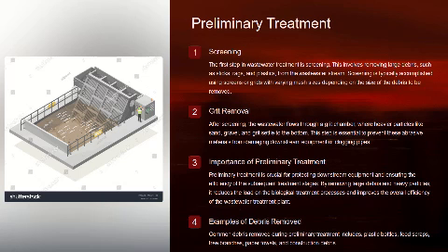After you're done screening, the wastewater flows through a grit chamber. And what happens here is that the heavier particles, like the sand, the gravel, the grit, settle to the bottom. The reason why you want them to settle to the bottom is because you want to make sure that these abrasive materials do not wear and tear down your machine, and that they don't clog your pipes.